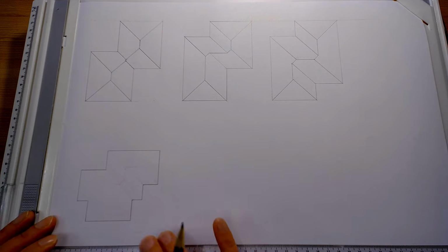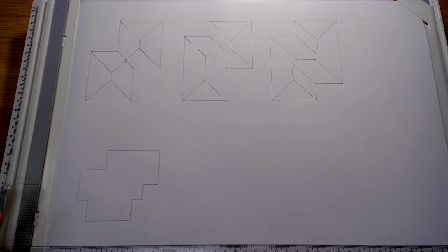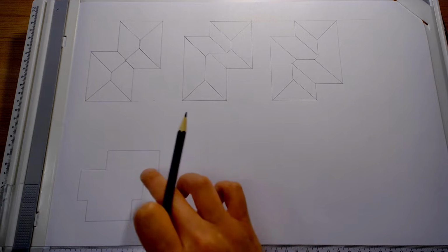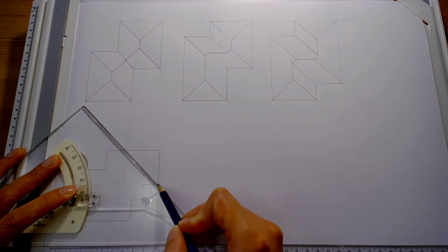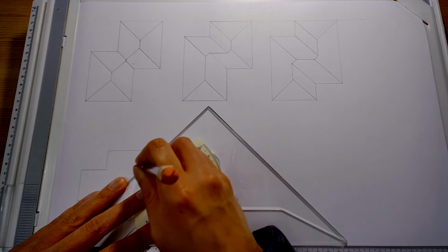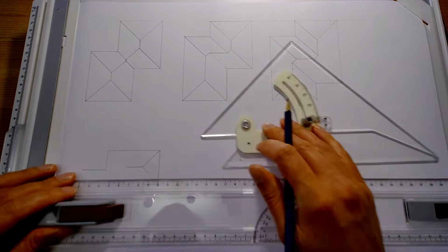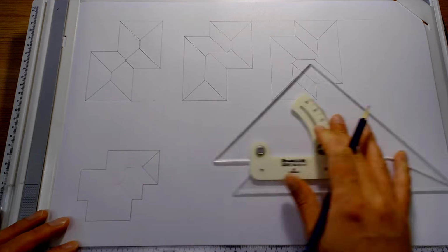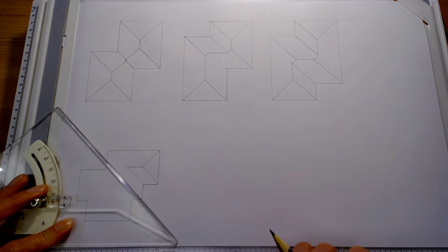But now we're just going to look at one more where this is a bit more complicated and a few extra shapes are involved. So again, let's split it up into rectangles. Okay, so we can see we've got a rectangle over by here first. So let's draw our first hip on that end of the rectangle with a ridge line coming off that, and based on the principle we've just looked at, it's going to hit this valley before it hits that hip. So let's draw that valley going up to the ridge.